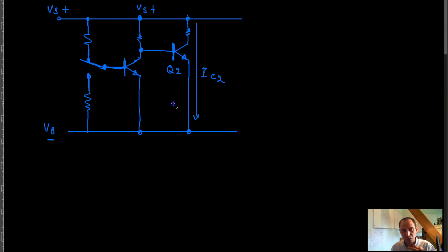Now, in order to understand this circuit and do the calculations, you need to understand how this voltage works, meaning that I can simplify this whole circuit. There's a transistor over here, a resistor that goes to the positive rail, and you can forget about this other resistor, it's not that important. The base of the transistor goes through a resistor to the positive rail, and the emitter goes to the ground. That's all this part of the circuit really is.